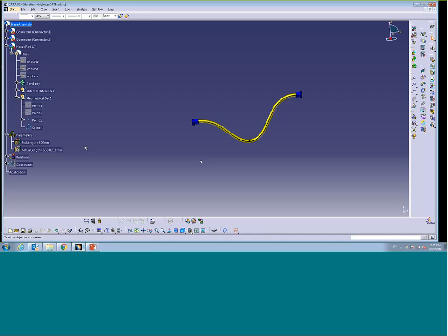Of course, I could go through a lot of pain, trying to adjust the location of this point, moving it back and forth until it kind of matches here, but there is a better way. I'm going to use optimization. How can we possibly use optimization? Well, what if we set up our goal as minimizing the difference between the standard length and actual length? So the minimum would be 0, right? If we run optimization, then it will try to match the actual length by adjusting the location of the sag point to the standard length. Let's try to do that.